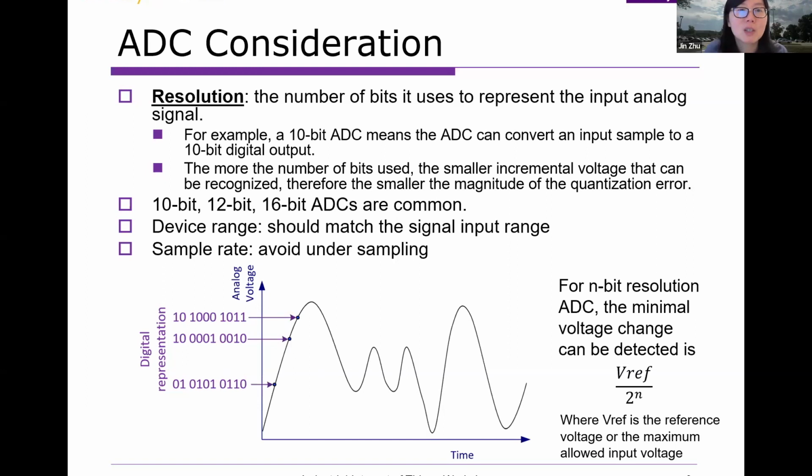So if we convert an analog signal to digital, we will represent it as shown in this figure. We represent any analog signal using some bits, simply some binary values. So if we talk about a 10-bit ADC, it means we are going to use 10 binary digits to represent the corresponding analog signal. The commonly used ADCs nowadays are 10-bit, 12-bit, or 16-bit. They could also have really high resolutions, like audio, which could be stored in 24-bit.